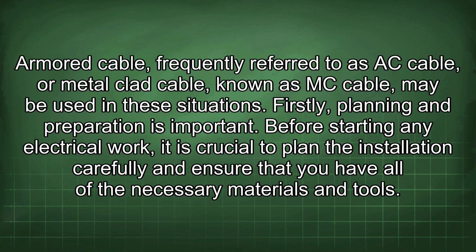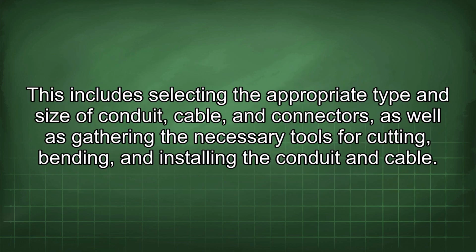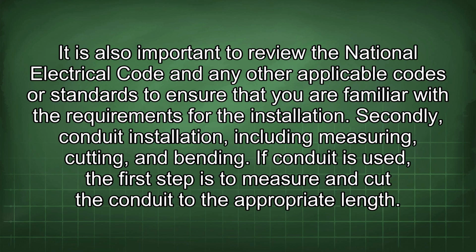Before starting any electrical work, it is crucial to plan the installation carefully and ensure that you have all of the necessary materials and tools. This includes selecting the appropriate type and size of conduit, cable, and connectors, as well as gathering the necessary tools for cutting, bending, and installing the conduit and cable. It is also important to review the National Electrical Code and any other applicable codes or standards to ensure that you are familiar with the requirements for the installation.